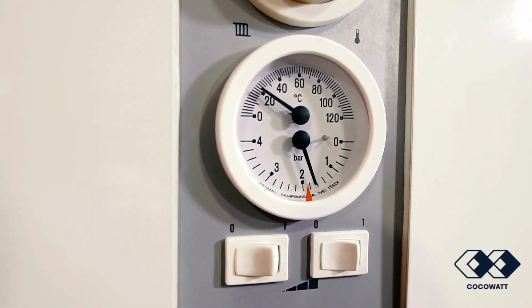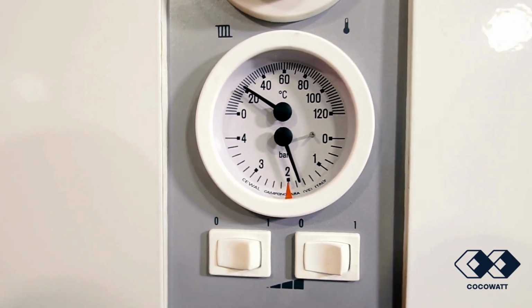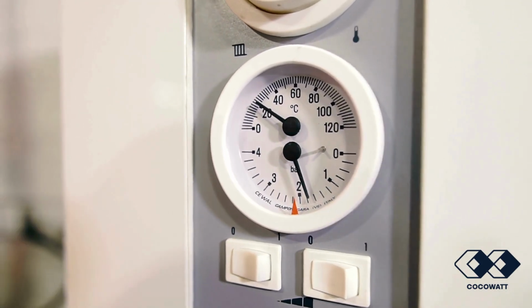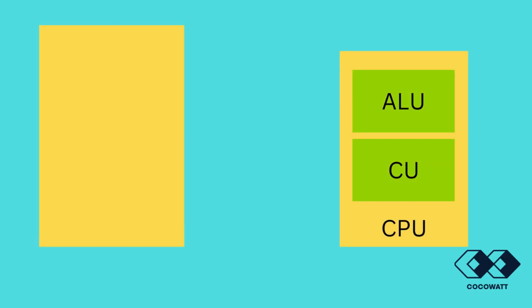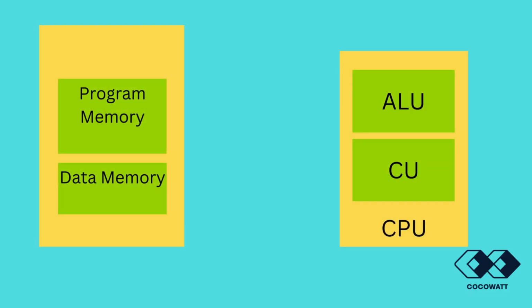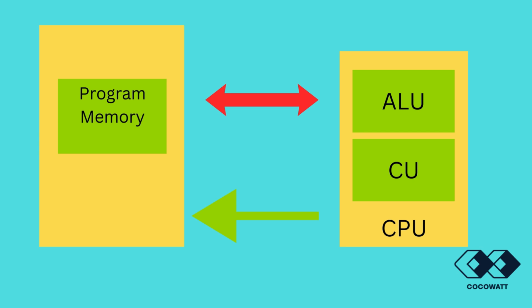Von Neumann architecture. Now, let us take the example of a simple temperature sensor system in a thermostat. In this case, speed is not as critical, so the microcontroller's single memory can store both program instructions and data. When the CPU needs to check the temperature reading, it accesses the shared memory, alternating between reading instructions for checking the sensor and reading the actual temperature data. This can create a slight delay compared to Harvard. Since von Neumann architecture uses a single memory for everything, it's simpler and often more cost-effective, making it great for devices where speed isn't the primary concern.